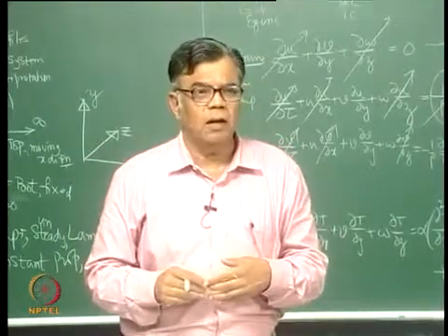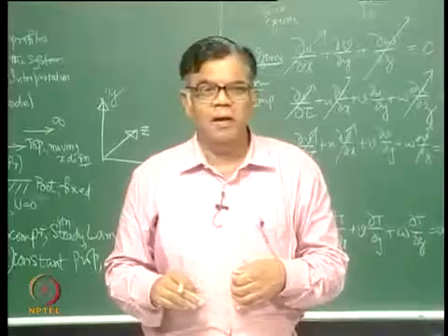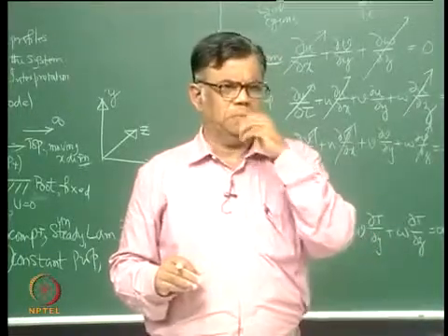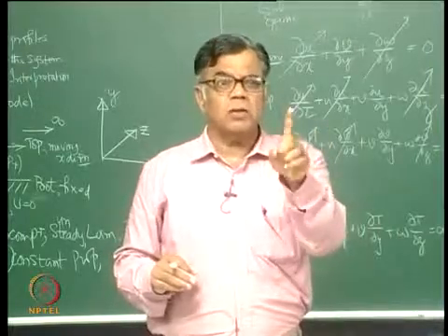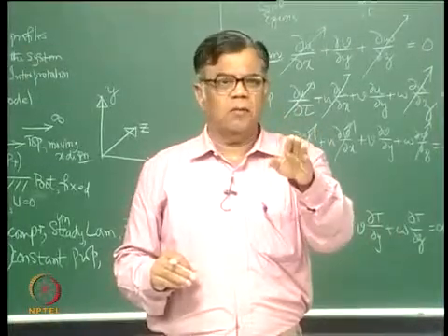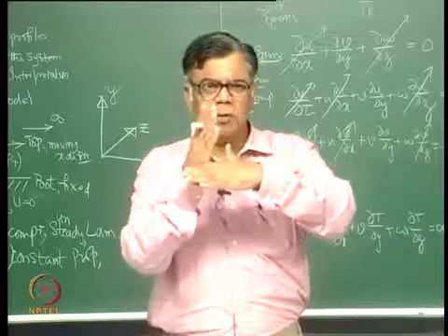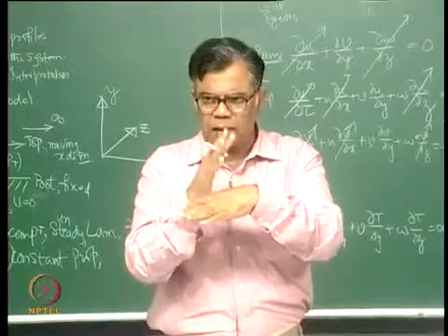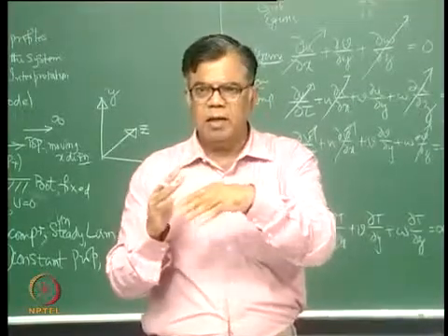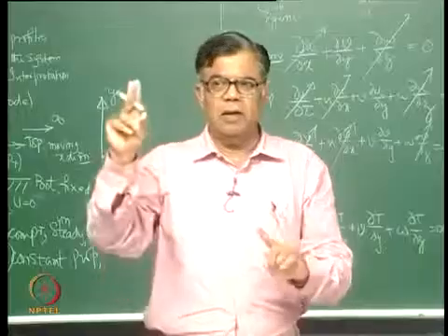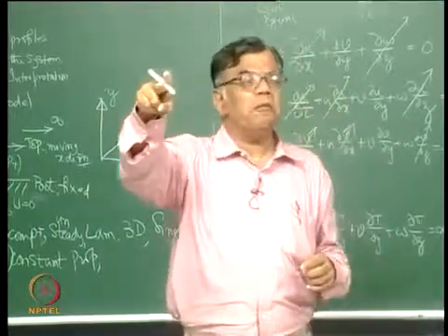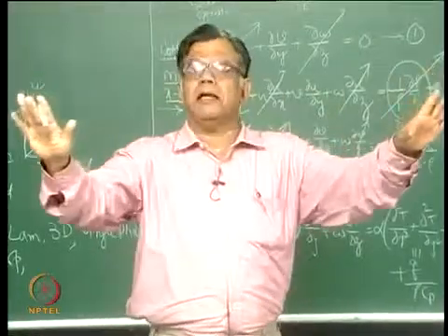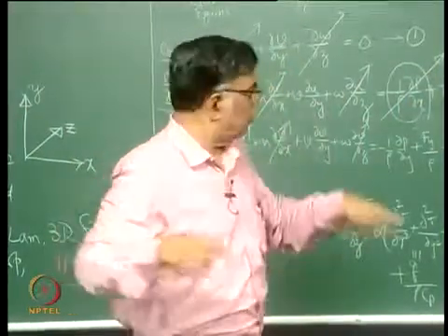Why? No penetration. No slip does not come under V; slip applies to the tangential velocity. V equal to 0 is perpendicular to the plate. So for V equal to 0, what condition do we have to specify? Flow is in one direction. There are no perforations, so there is no V component, meaning it is a solid, impermeable plate. We should have written that here.